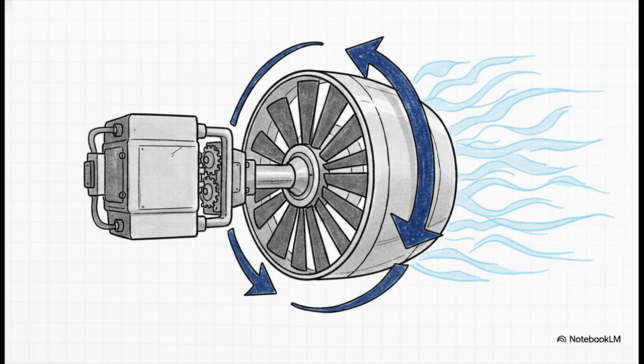But turbine starting? Oh, that is a whole different beast. You cannot just bump the starter on a jet engine and walk away. It requires sheer, continuous mechanical effort. The starter basically has to forcefully drive the heavy compressor section up to a tremendous rotational speed. And only when sufficient airflow is moving through the engine, fuel is introduced, and ignition is finally achieved, only then can the engine start to self-accelerate. If the starter drops out even a second too early, you'll have a very expensive aborted start on your hands.